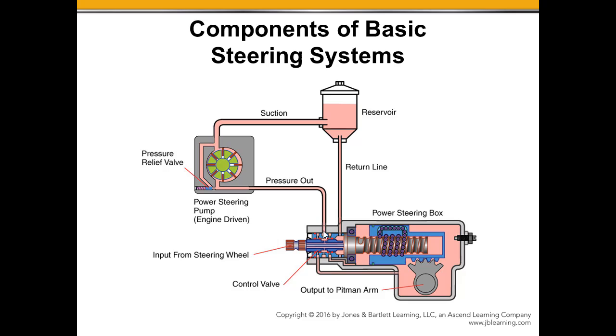We've got pressurized fluid coming into the center here, and depending on if we're making a right or left hand turn, it will direct that oil through internal passages, through this line, pressurizing this side, working around here, and now that pressurized oil is working against this surface of the piston here and here and here to assist that steering piston to move back this way to the left.